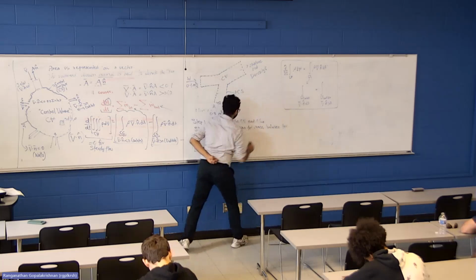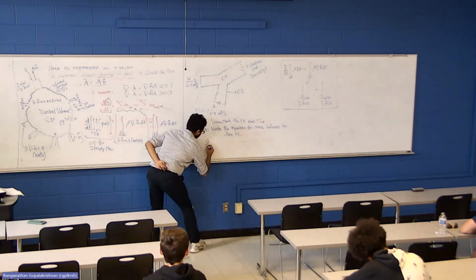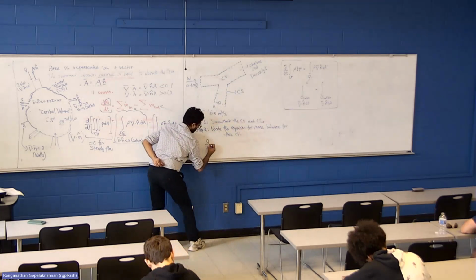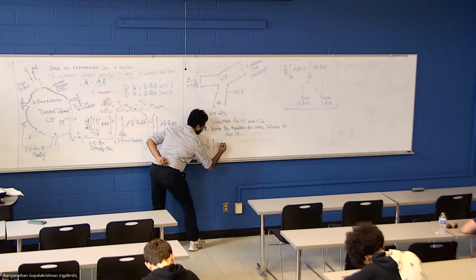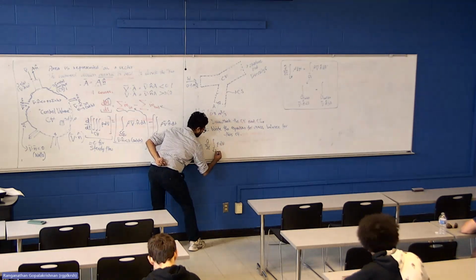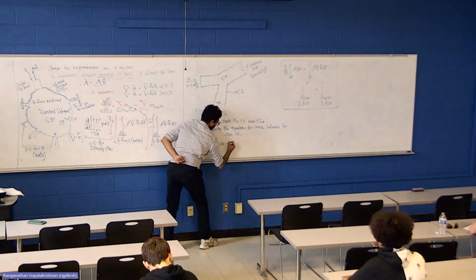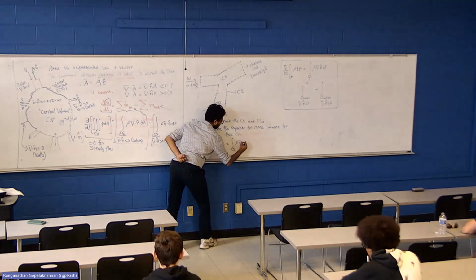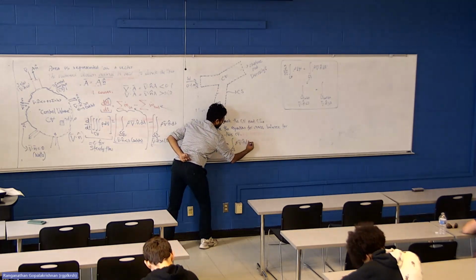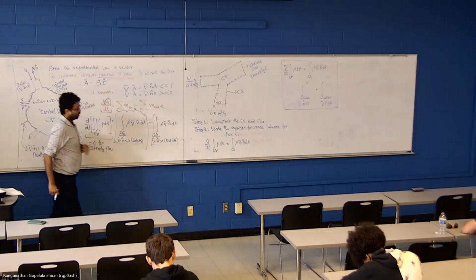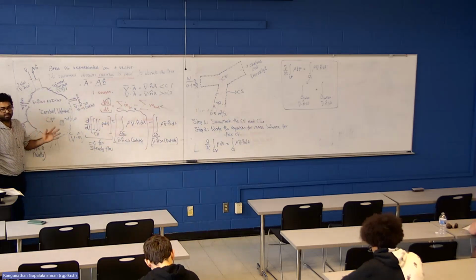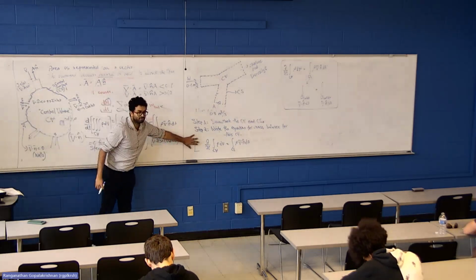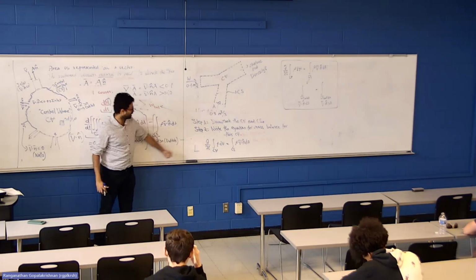It's basically this equation: the derivative with respect to time of the integral of rho dV over the control volume is equal to the integral over the control surfaces of rho v dot n dA. Now this is where we are going to unpack how to use this expression. So far I have just shown you this expression.